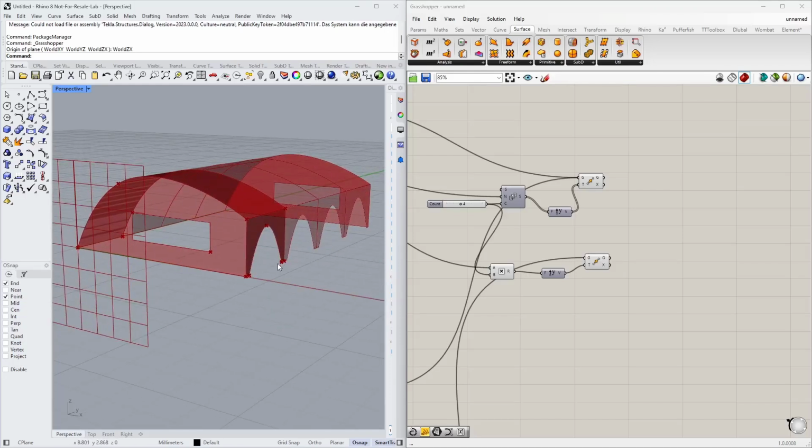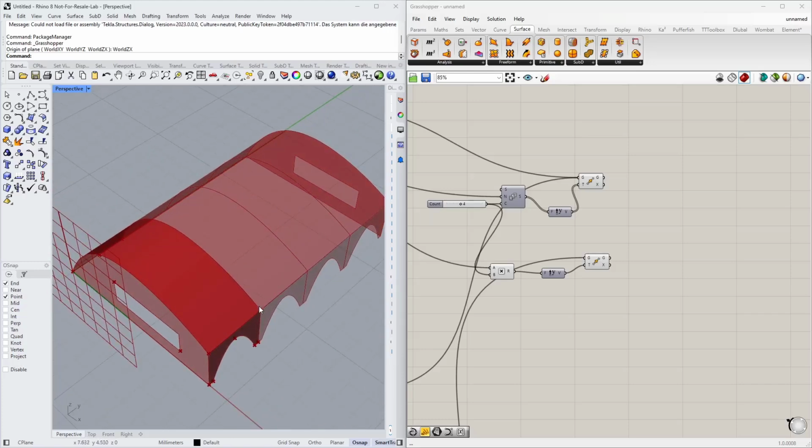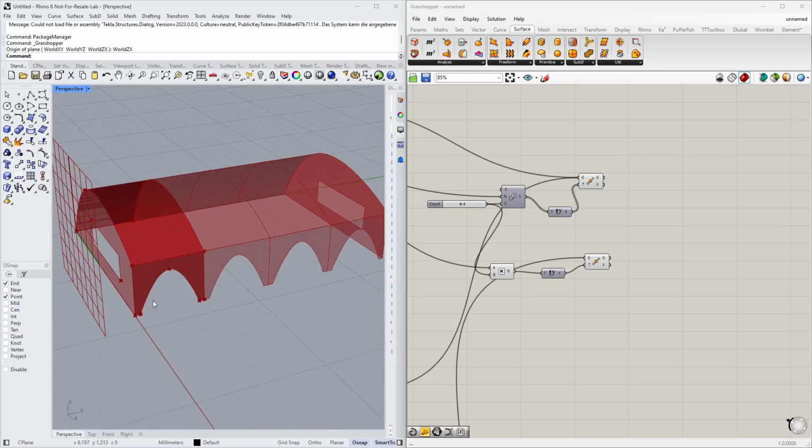And I can use these lines in my line support component to export it to RFEM6 afterwards. Additionally, I need these 3 internal curves, because I want to assign a member or a cross section to them. And maybe also a collection of all of the surfaces that I have.